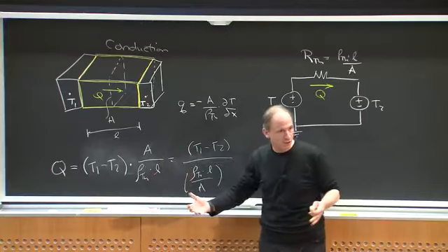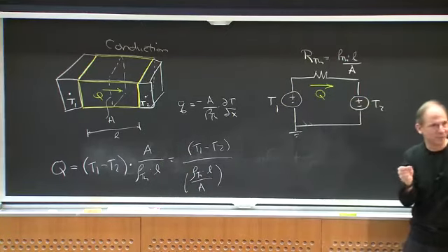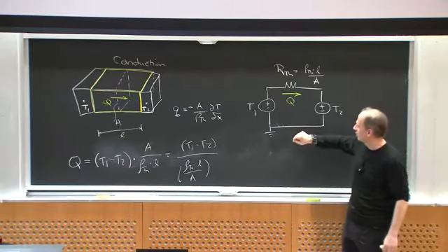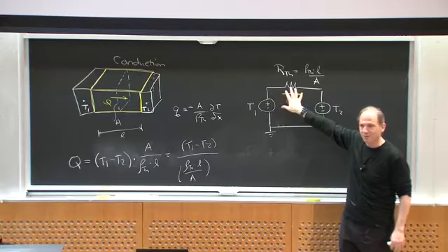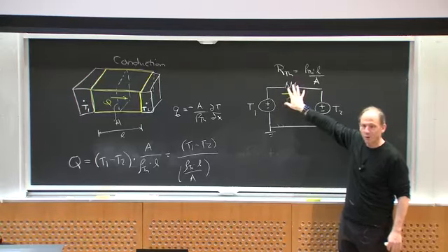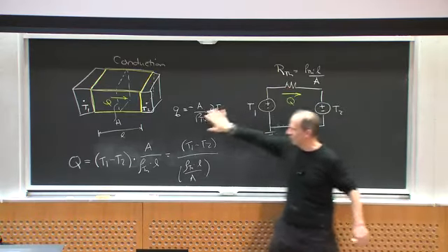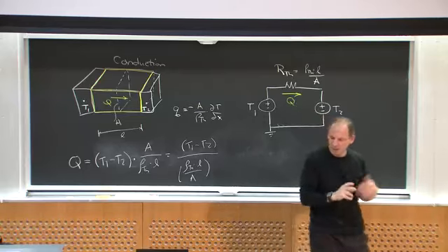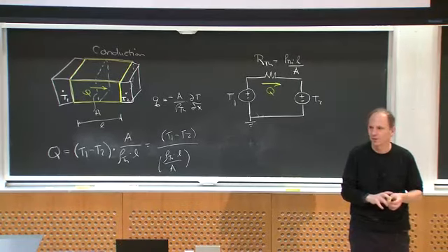The reason this works is sort of temperature is conserved going around any loop, right? If I measure temperature differences around a loop, I ought to get zero. And if I consider heat inputs and heat transfers, conservation of power is sort of the equivalent of KCL in the circuit model. So I'm showing you a simplified circuit model for a very particular kind of heat transfer, but you can use this model to represent heat transfers in a variety of conditions. Any questions about that?